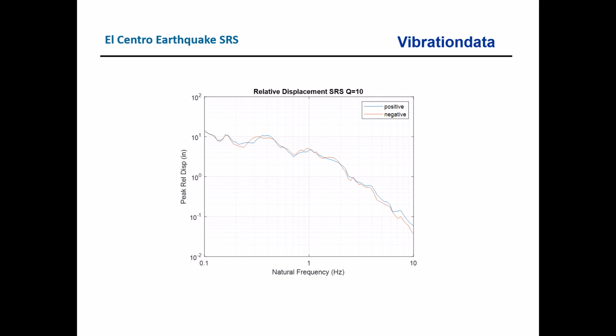Depending on the sensitivity of your structure, the type of structure, the type of ground and the foundation, and quite a few variables at work, but damping plays a role too, you may prioritize one of these three metrics over the other in terms of relative displacement, pseudo-velocity, and acceleration.